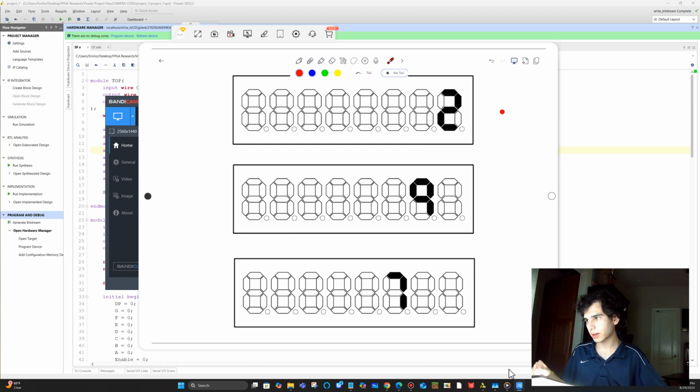If you go super fast, like at 100 megahertz, nothing will turn on because the values will be changing so quickly that the 7 segments will not have time to drive their values. But if you go too slow, then you'll visibly see it changing. So that won't be good.